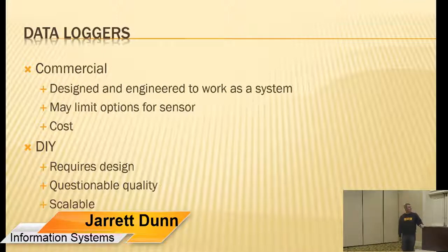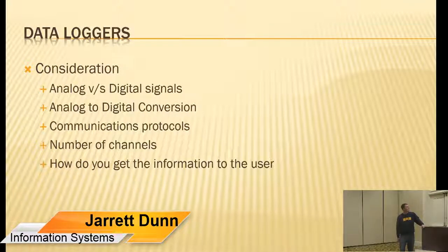There are also a lot of options to DIY. We have an entire lecture on that after lunch, but the DIY benefits are they tend to be cheaper, you can customize them for exactly what you want, and you can mix and match parts to make it work instead of being tied to one company's ideas. When thinking about data loggers, you need to think about whether it's analog or digital, the communications protocols, whether you can talk to the things you want to, the number of channels, and how you want to get the information to the users.